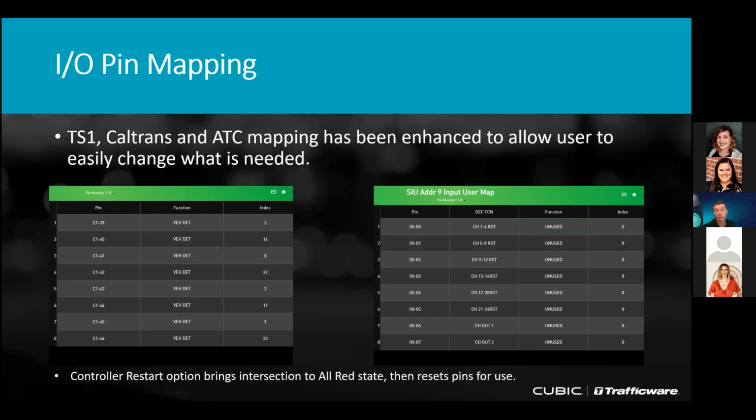A controller restart option was added. This is how you accept pin changes. Another little added benefit, it causes the intersection to go to an all red state, which makes it a pretty safe way to put an intersection into Flash for technicians.